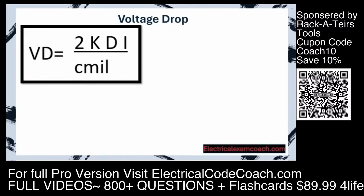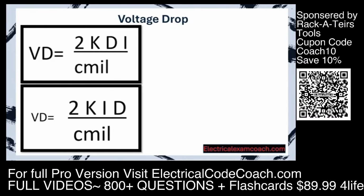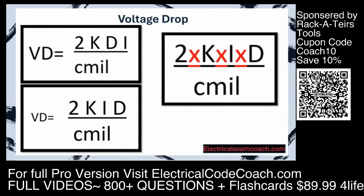But I've rearranged it so it's easier to remember. I do it like this: 2KID over C mil. Easy to remember and easy to plug in. And what this is, just like previously in the program, is implied multiplication. So it's going to be 2 multiplied by K, multiplied by I, multiplied by D, divided by C mils.